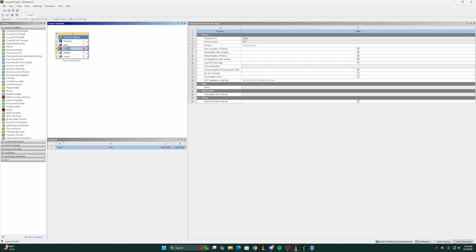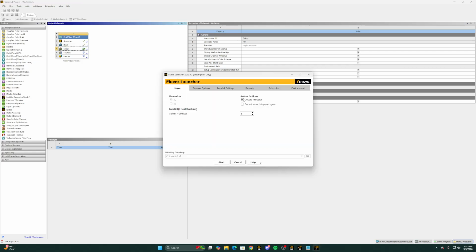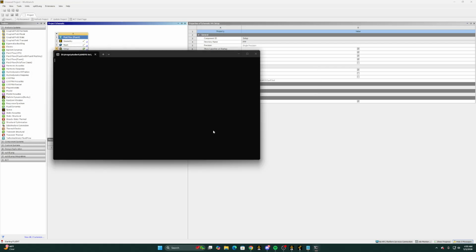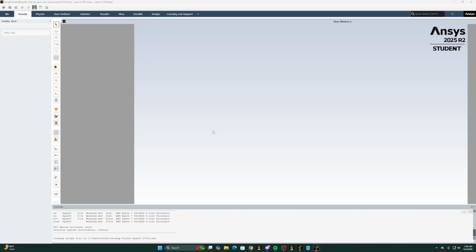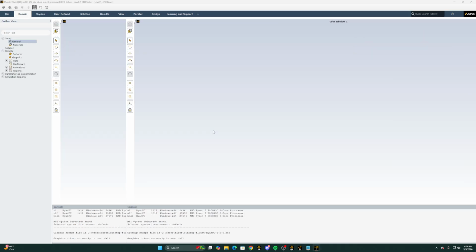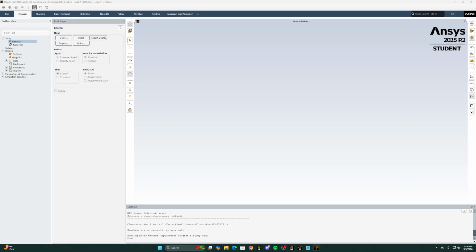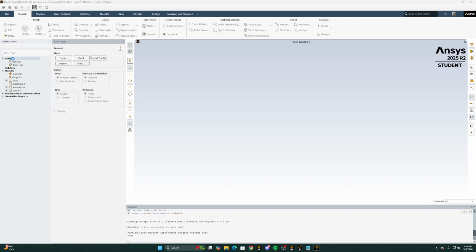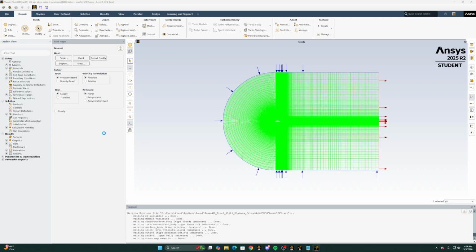And now we're on to setup. So we're going to double click this, double precision. You can use any number of these solver processes. I recommend over 2. I'm just going to start with 3 here. If you do less than 2, it's just going to take a long time to calculate all the convergences. Nothing really bad, it'll just take longer. So we're going to let this load for a little bit. Okay, so now this is loaded.